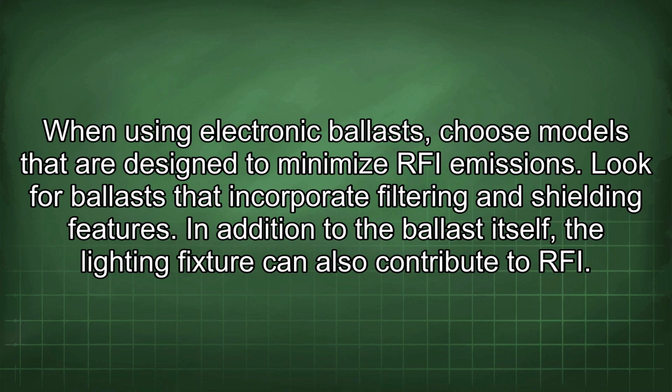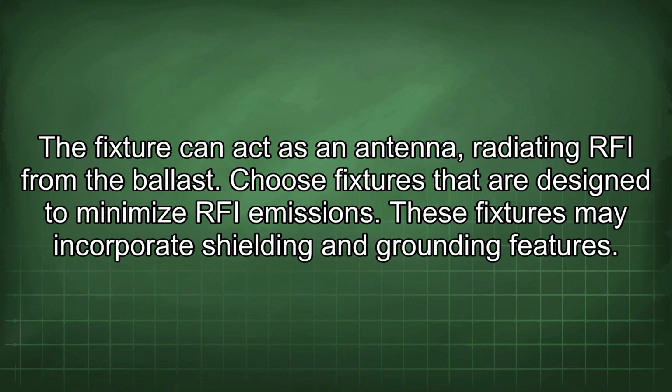In addition to the ballast itself, the lighting fixture can also contribute to RFI. The fixture can act as an antenna, radiating RFI from the ballast. Choose fixtures that are designed to minimize RFI emissions. These fixtures may incorporate shielding and grounding features.